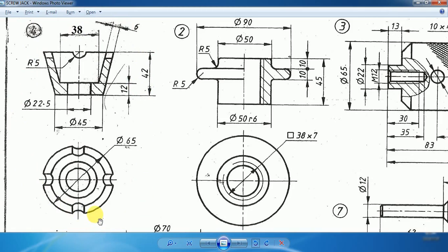Whenever we want to use the revolve feature, similar to how we modeled the body, the nut, and the screw spindle, in the same way we can model the cup also. But when we want to model this cup with the help of the revolve feature, it is important to create the right profile of the cup or the left profile of the cup about its axis. So this is the axis, and with respect to this axis, this is the right profile. Therefore this right profile will be constructed in the front plane.